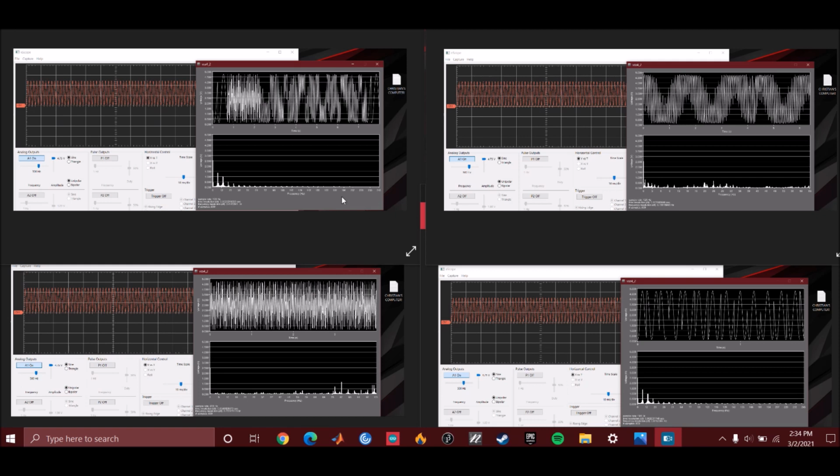Now we'll get the 300 Hz sine waves. So we have aliasing around 100 Hz. We see a cleaner sine wave of 142, since we get a Nyquist frequency of 150, and those are pretty close. And then we see more aliasing around 200 Hz and 500 Hz as well.